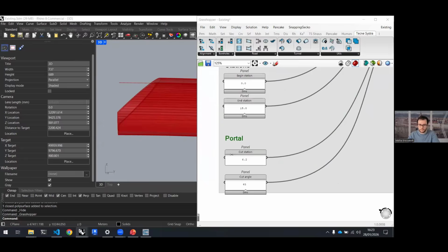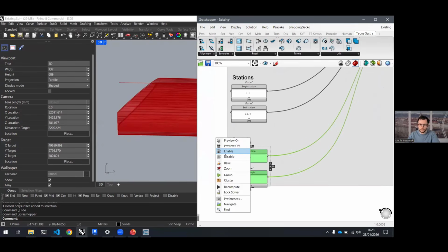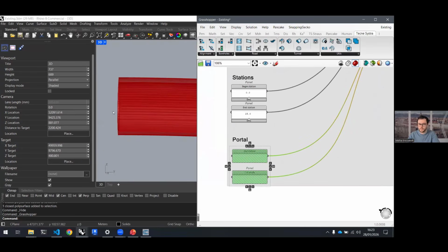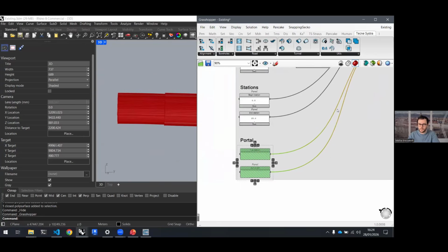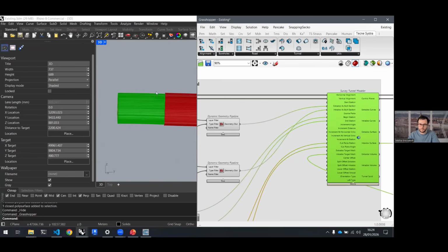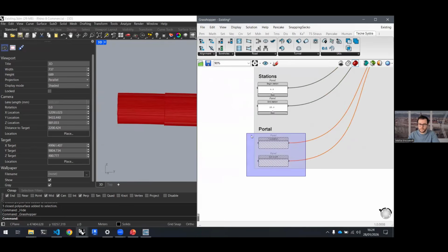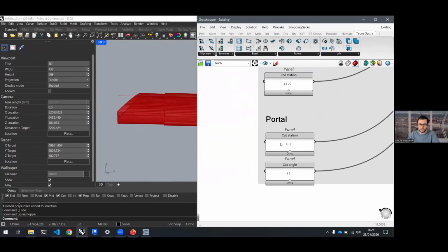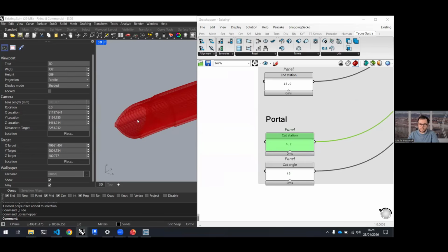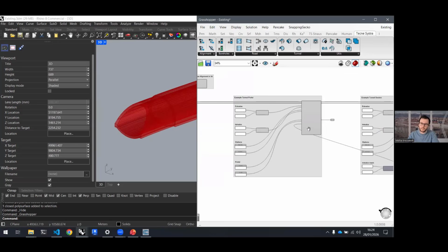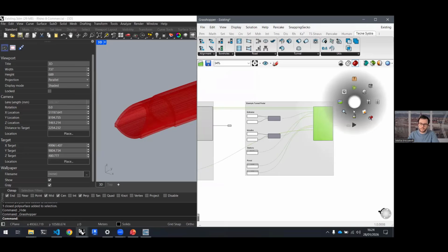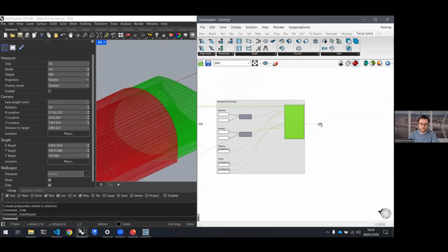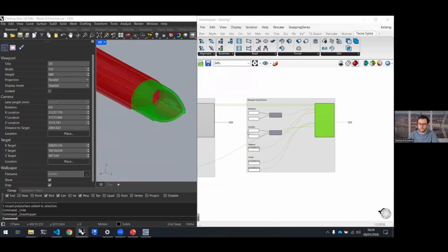So we have also a polyline. Actually, let me disable this. So you can see this is the default piece without cutting it. So from 0 to 15 meters. And then we can specify there an amount of meters where you want to put a cut plane, and the cut plane angle, 45 degrees in this case. And you have this slanted cut here. We did the same thing on the other side. So this is the same on the other side for the other piece of tunnel.